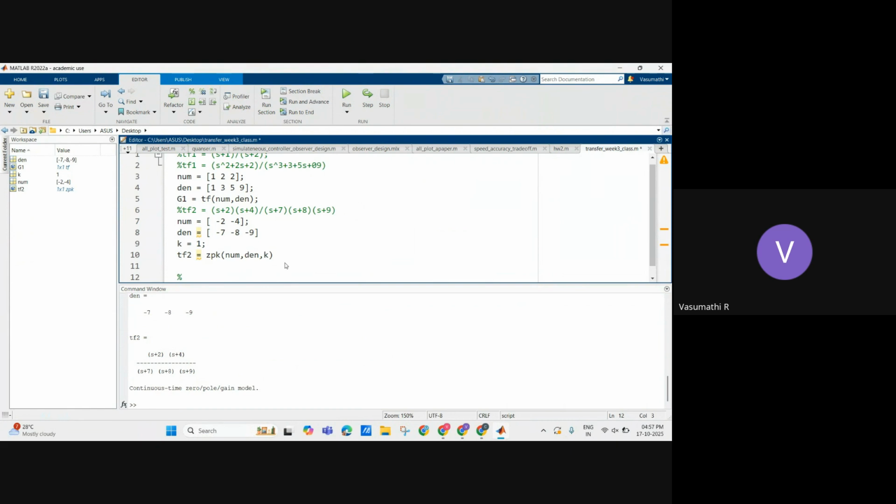So for the first step, I can use the same transfer function like this here. I'm going to use one keyword: s is equal to tf of s. Whatever s you are considering, consider that as a part of a transfer function. That's what this line tells MATLAB.